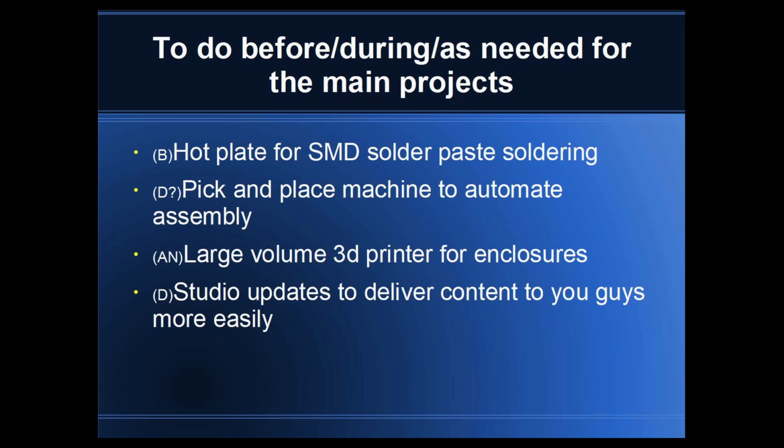Yeah, so there's a need for, what's the best way to say this? I guess control and stability on the temperature. With the hot air gun, I haven't quite gotten it nailed down to what the temperature needs to be and how low the flow of air needs to be, because I wound up pushing parts around as things heated up, and as shaky as my hands are, I did a better job with that than I did with the hot air stuff. So a hot plate, I think, will be a better way to go.